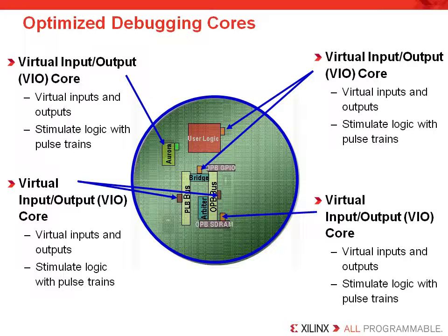The IBA, or Integrated Bus Analyzer core, is an optimized embedded designer's core that is used for building designs using the Xilinx MicroBlaze soft processor core or a dedicated PowerPC core. The IBA core allows designers to analyze PLB or OPB bus signals and offers protocol detection, which is necessary since embedded designers are often testing their custom peripherals using ChipScope. ChipScope makes it easy to sample the most commonly sampled signals on these buses, such as control, address, and data signals associated with these buses.